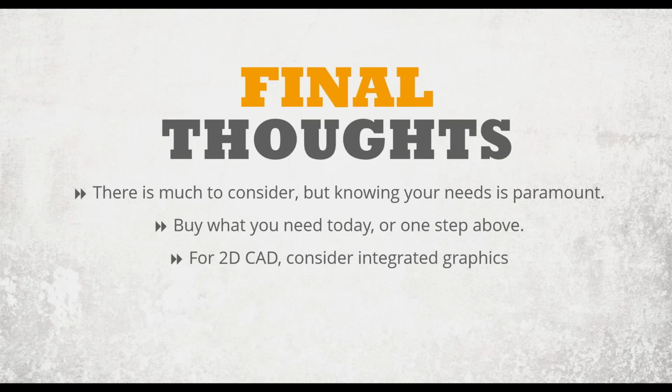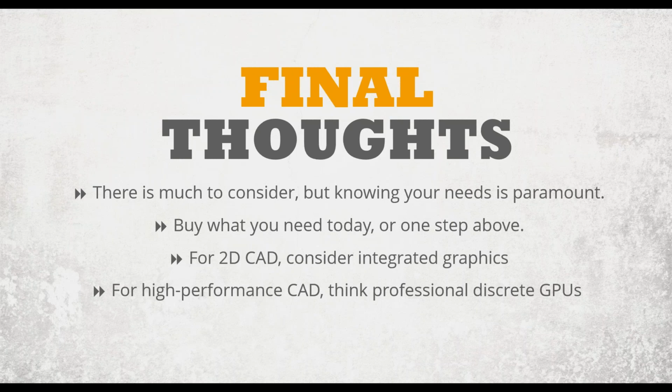For 2D CAD, principally AutoCAD and MicroStation, you may want to consider integrated graphics because they may very well be all the performance that you're going to need, at least for now, and you can plug in a discrete GPU card later. For high performance CAD, think professional discrete GPUs. That has not only to do with performance, but it also has to do with longer term reliability of drivers and making sure that the software manufacturer is actually testing with that GPU to minimize the possible downtime that you could experience in the future.